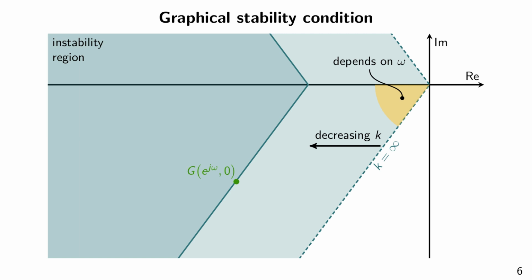To derive the result, let me go back to the graphical stability condition used to obtain the slope bound for the nominal system. When the system is uncertain, the frequency response extends from a single point to a domain on the complex plane. It is proven in the paper that the frequency response of the uncertain system for all allowable values of the uncertainty is a disk such as this one. The response of the nominal system is not necessarily in the center.